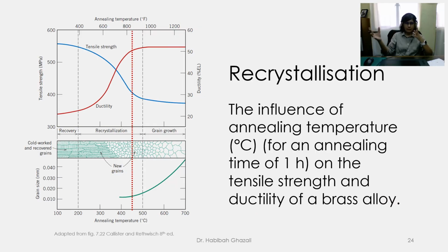So by looking at that difference between when we anneal materials at different temperatures, the grain size will be different at a different time. If we anneal them at a higher temperature, the grain will grow. The grain growth is at a much faster rate. So of course, the mechanical behavior will be different at a different annealing temperature.